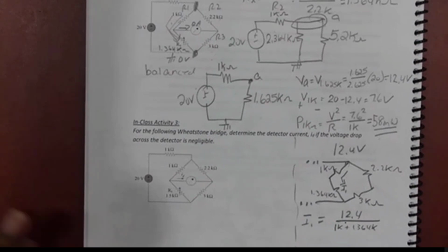So if I call the current down the left branch I1, then I1 is equal to 12.4 divided by 1K plus 1.364K. The voltage across those two series resistors divided by the resistance is the current. That's Ohm's law. I equals V over R. So that current is,